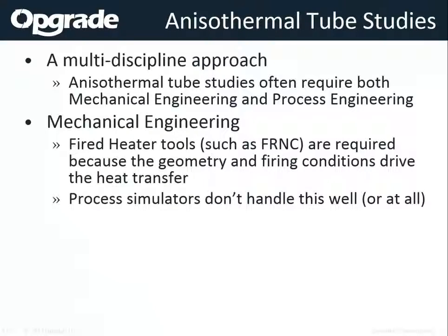Mechanical engineering needs to do the heater tool to give you a much better indication of the heat transfer going inside that tube. And it's almost done on a tube-by-tube basis. Usually that's what we recommend. On a tube-by-tube basis, you take the heater information from mechanical and you put it into a process simulator, and you iterate back and forth until you have a very good profile going down between them.